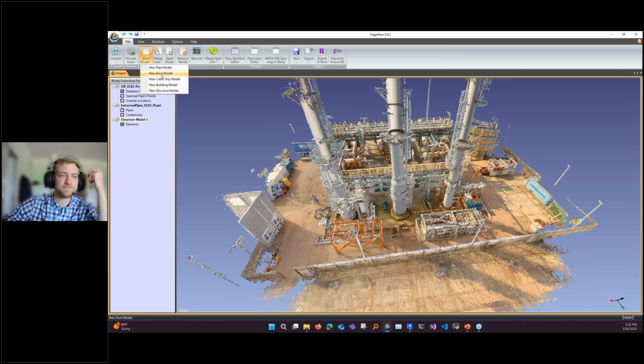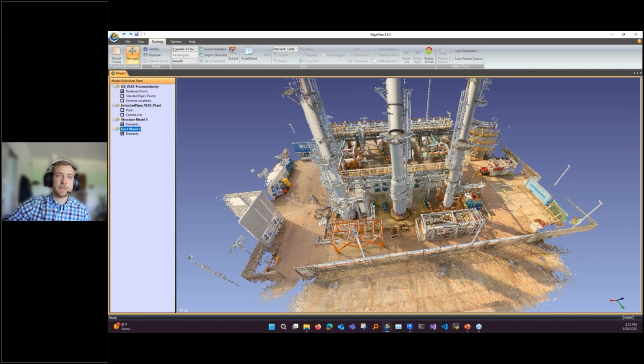element to click on. And then, if we click on this, we're going to see ducting up here. And the same thing for cable trays. These are going to actually give us the tools for it. And it's going to be the exact same extraction function. The only difference is going to be the connection tools. And the big tip there is just use the align functions a lot more to get things squared up before you do the connections for the elbows and things like that, and transitions.